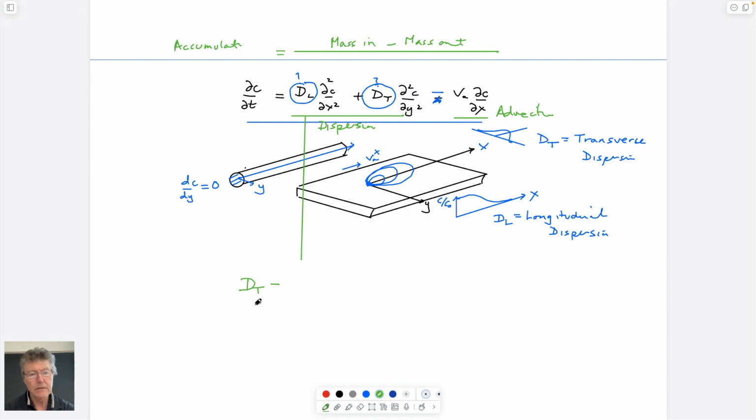longitudinal. So longitudinal dispersion coefficient is equal to longitudinal dispersivity, which is a coefficient that describes our aquifer, multiplied by the advective velocity, maximum in the direction of that flow, the maximum one in this case, plus the diffusion coefficient multiplied by some parameter that corrects for the fact that it's flowing in and out of the pore space.